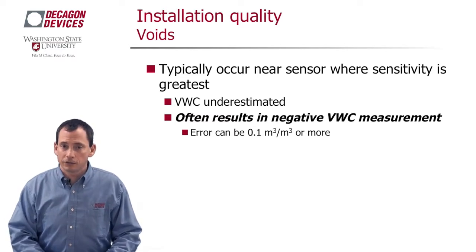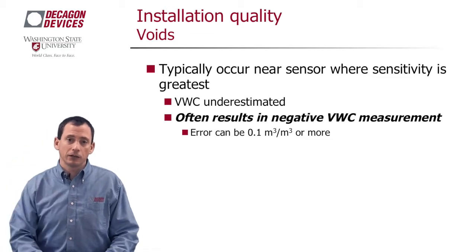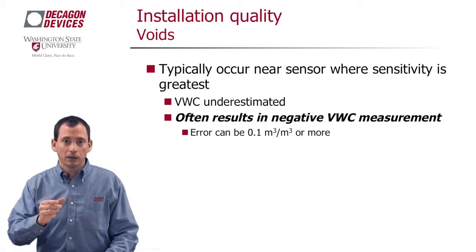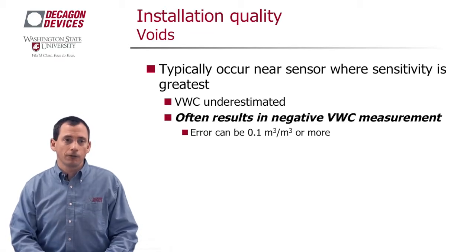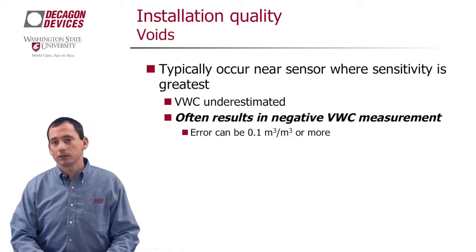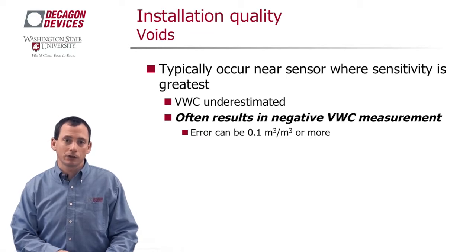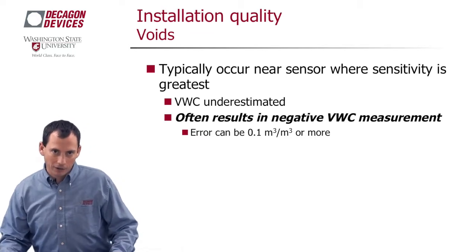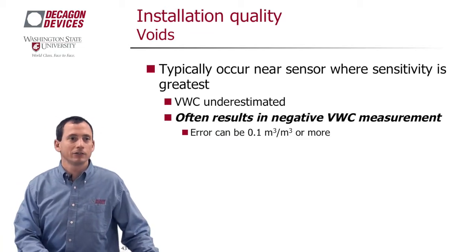We've had instances where worms have come and burrowed right up against the edge of the sensor and left a big biopore there, a big air-filled void, which will give a negative measurement. And so we've certainly had a lot of instances where you dig down and you look at the sensor and you can see pretty much immediately what's going on. It's actually interesting what you see when you get in the soil and look at what's going on around your sensors.